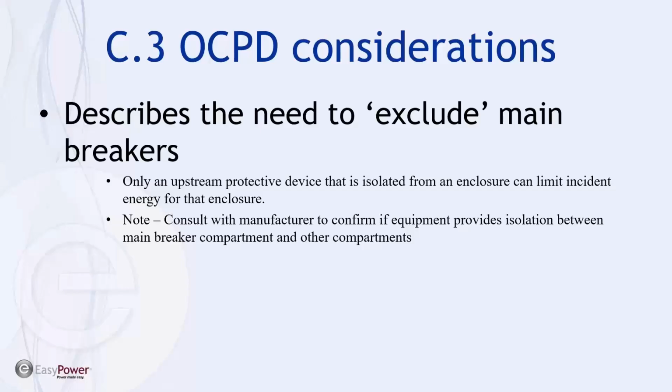terminals for a breaker. And if you look in manufacturers' catalogs, they end up being a small piece of plastic that form fits over the incoming terminal of the main. The purpose of those is to prevent incidental or accidental contact with the voltage, which is well intended and a very useful safety device, but it doesn't provide anything in the form of an arc barrier. So keep that in mind as you're looking at new installations, in fact.